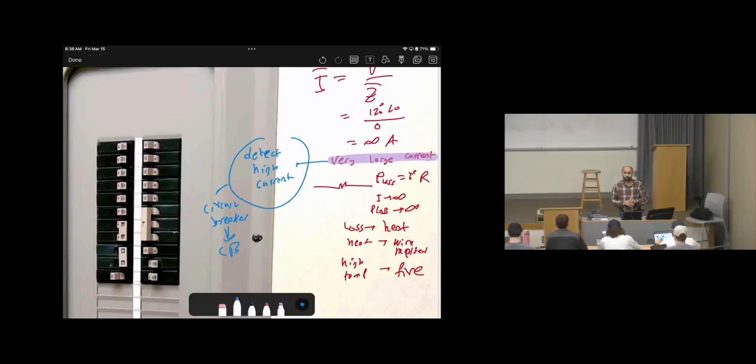That happened to me once, actually, I think last year. I was fixing a light bulb, and then a short circuit happened, so the power was off for the whole home. I went to the breaker panel and saw the main circuit breaker was off, and the circuit breaker associated with that room was stuck in the middle, not moving for a little while.